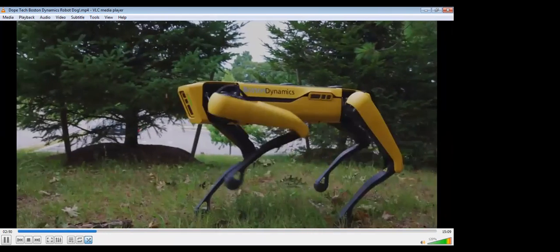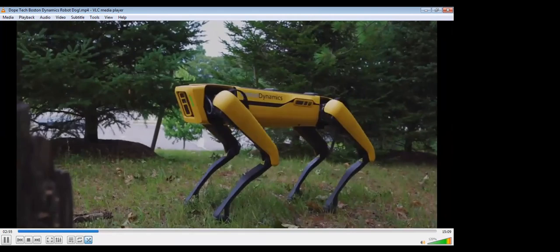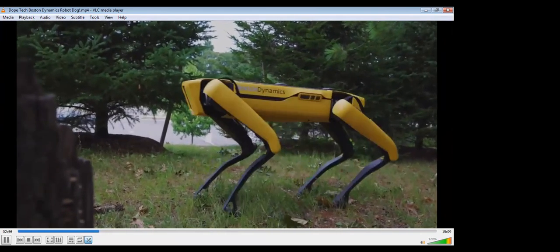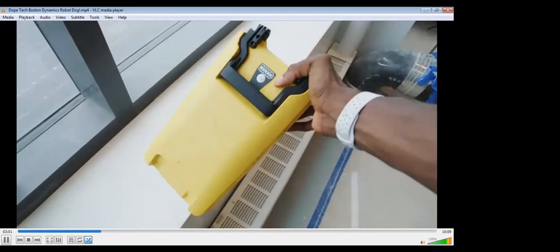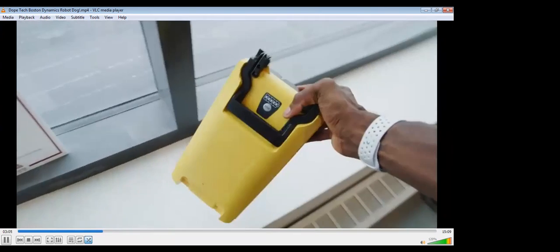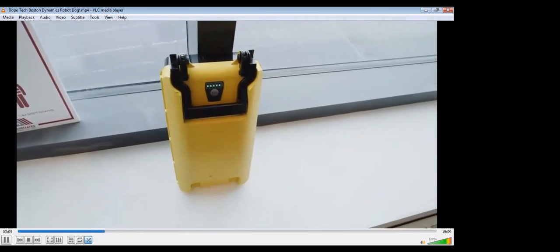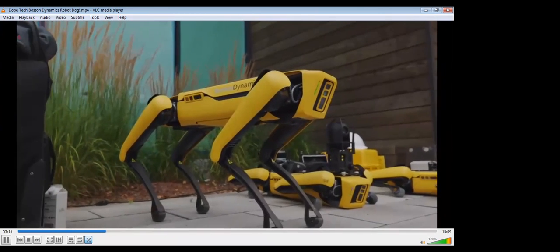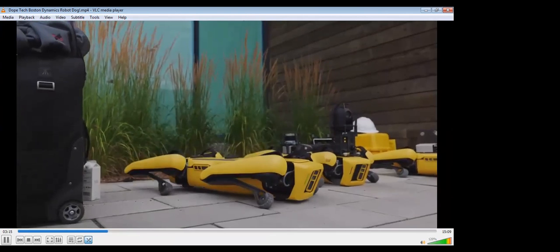Maybe the best example of that is the battery, actually. So Spot has a little interchangeable battery in the belly area. It's an 11,500 milliamp hour battery pack, and that powers Spot for around 90 minutes on a charge. But that, of course, depends on the payload weight and how much you're actually using it. As a matter of fact, Spot is actually using energy here, actively balancing, even when it's just standing still. So your mileage may vary.